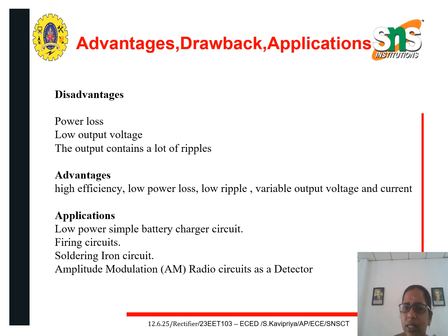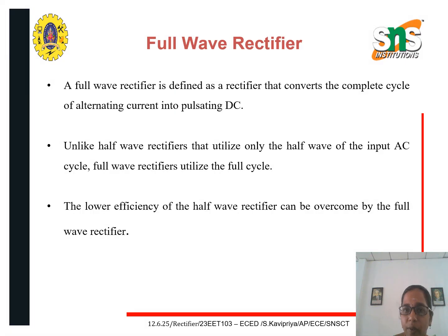It is a very simple and basic form of rectifier. So it is employed in low power simple battery charger circuits, in soldering iron circuits, in firing circuits, and it is even used in AM modulation circuits as a detector. And next is the full wave rectifier.